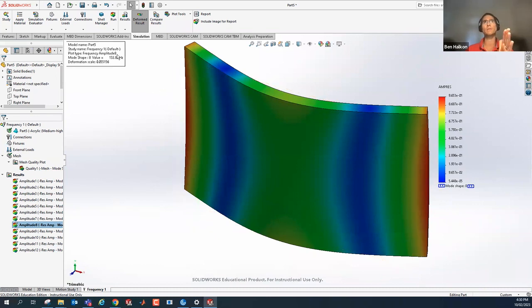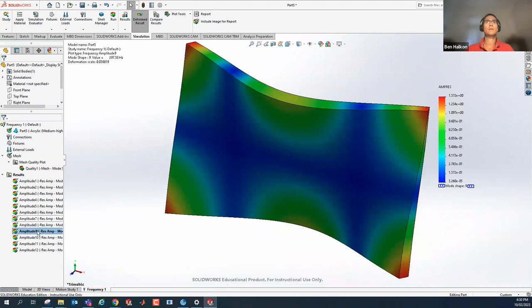You need a fine frequency resolution to be able to do that. And so that's part of the point of the exercise, is to be able to compare and contrast those 2 relatively close bending and torsional modes. This 9th or 3rd flexural mode is what I would call a second torsional mode. So you can see these adjacent corners are out of phase with respect to one another in terms of the motion. And there's like a nodal line running here and through the center.